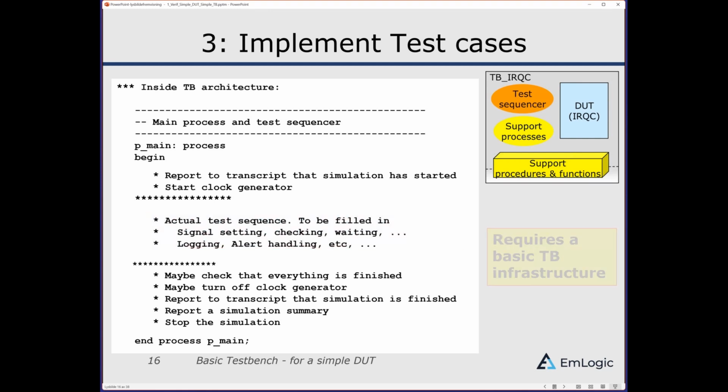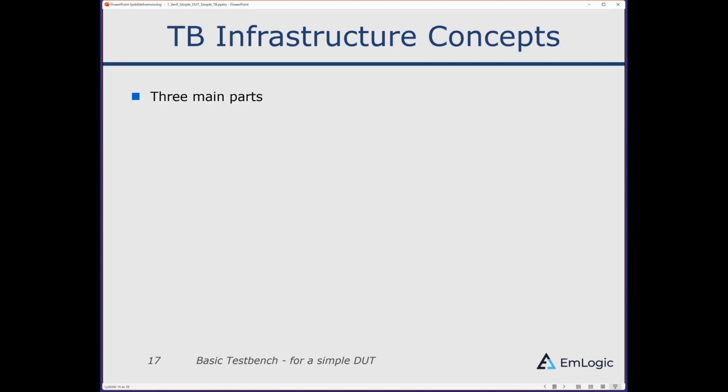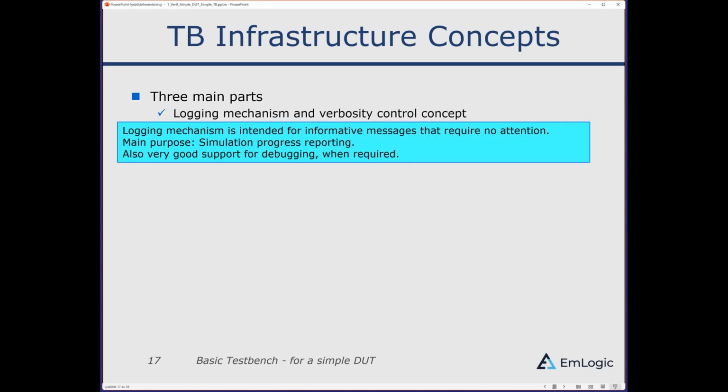In my opinion, this should start with a report to the transcript that the simulation has started. I think that is important because that means I can see that it has really started. It's not waiting for something to happen. And sometimes also maybe start the clock generator. And I always end the simulation by maybe checking that everything is finished, maybe turn off the clock generator, but at least report that the simulation is finished and report the simulation summary, and then stop the simulation.